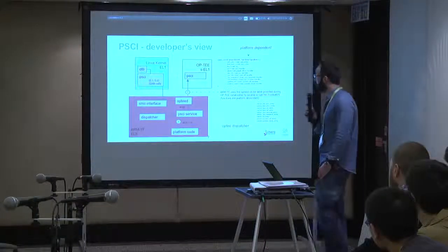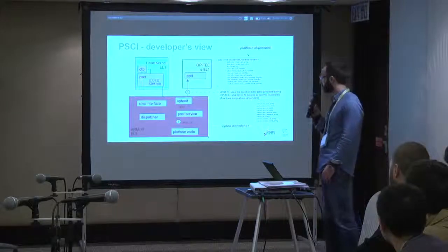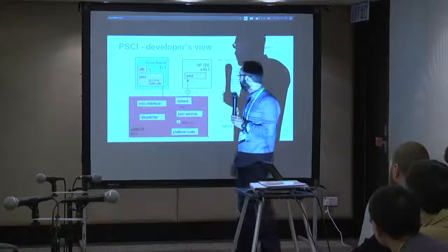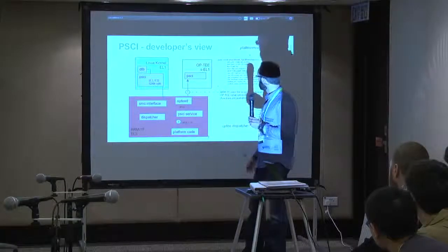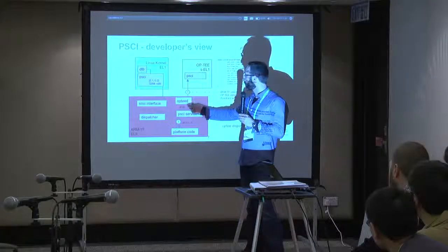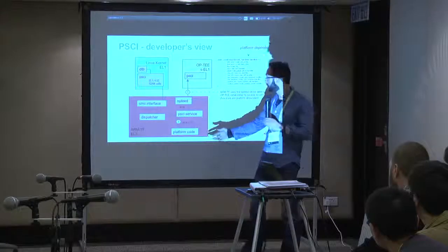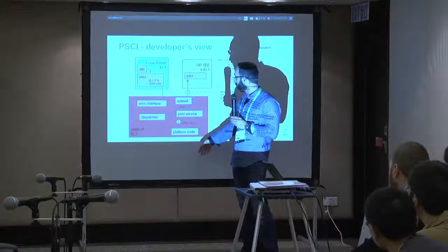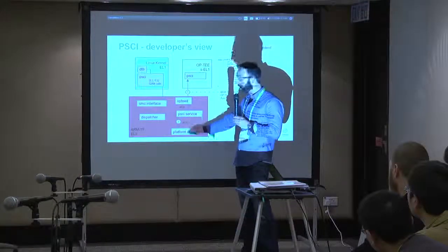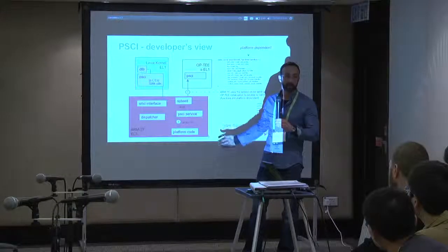And then the way it communicates, if you've got an ATF present, which is the case here, it goes over the SMC interface. It will call the dispatcher. If you register your PSCI service, which OP-TEE does, you have a dispatcher for the OP-TEE for Affinity 0, which represents the core. And the rest of the PSCI service calls for the rest of the platforms, so Affinity 0, 1, 2, are handled in the platform-specific code for your system, for your SoC.